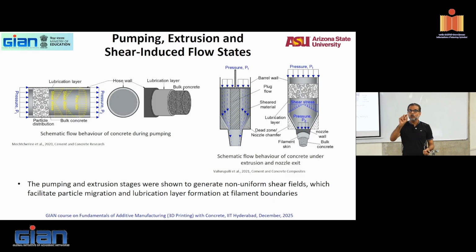You have now 2 times the thickness of the interface, where the lubricating layer has a massive effect on the properties. Was the lubricating layer good for us yesterday? Good. Why? It helped you extrude consistently and nicely with low energy. Is it good today? No, I don't want it really today, right? Now see the conflict between extruding and the properties that you want.